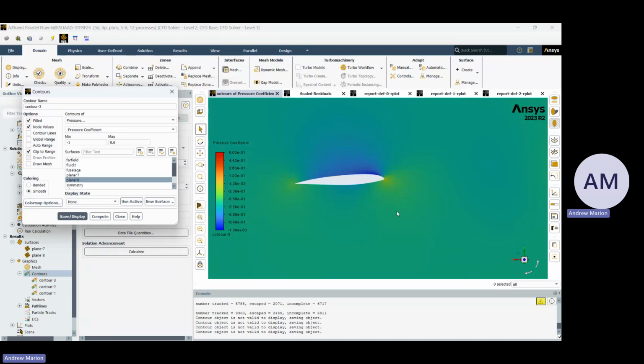Sometimes your visuals are what's going to screw you over in Ansys. You could be getting correct results but everything just looks green. I can't tell what's going on. It's all green. So going in and editing your scales can give you a better showcase of the color contours to give you a better idea of what's going on.